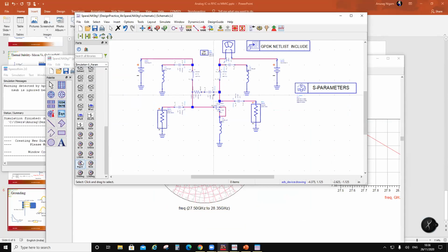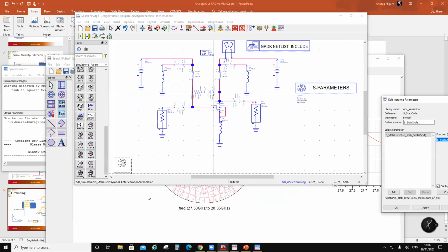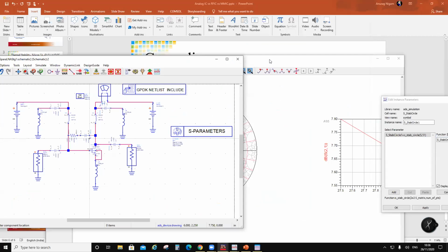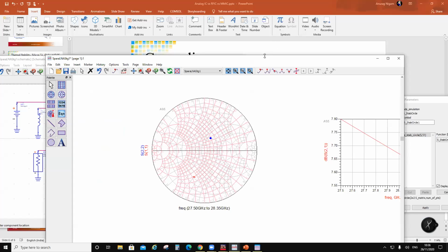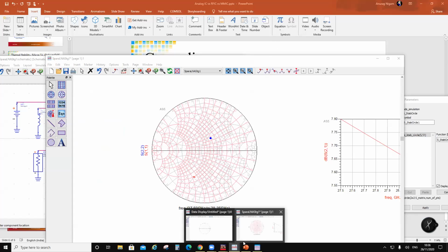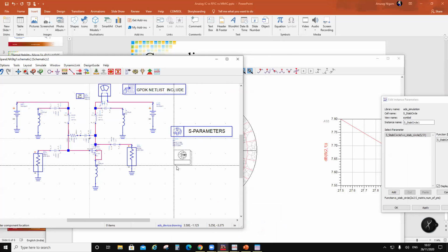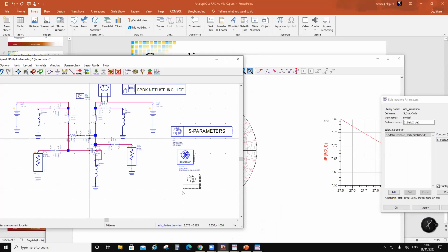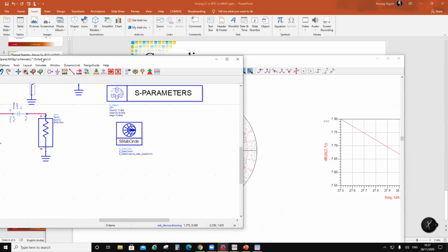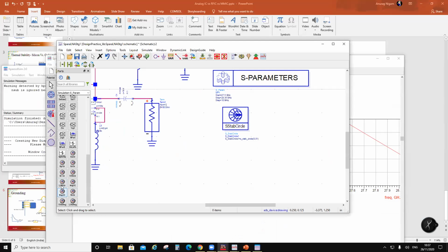These are contours which join all the impedances where the reflection coefficient becomes 1. So now, depending on whether the center of the Smith chart is inside or outside that circle, you can predict which part of the Smith chart is unstable. So where were we? Okay, source stability circle and load stability circles.